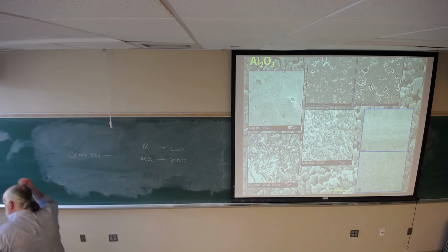All right. So there's a small company down the street who makes those. They start with the powder. They make a preform, isostatic press it, and then they sinter it. And they run into problems in processing also. But same problem that we have with aluminum.